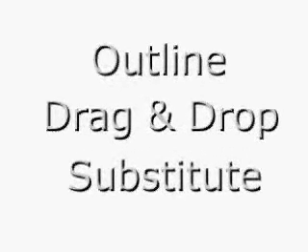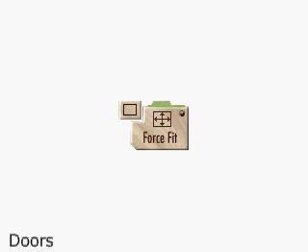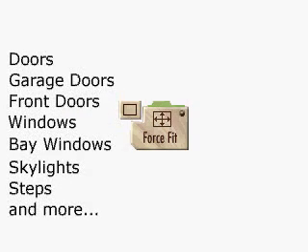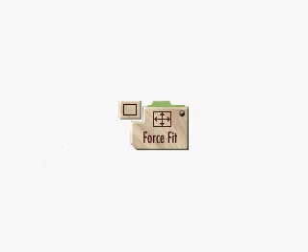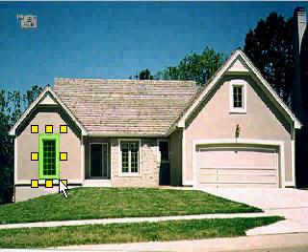The basic concepts are outline, drag, drop, and substitute. Use the rectangle force fit tool to create areas for placing windows, doors, or any image library item. The item you choose will take the exact height and width of the area you create. In this example, we will use a window. Click the crosshair's cursor once to anchor it and begin the outline. Drag to the opposite right corner and release the mouse button.